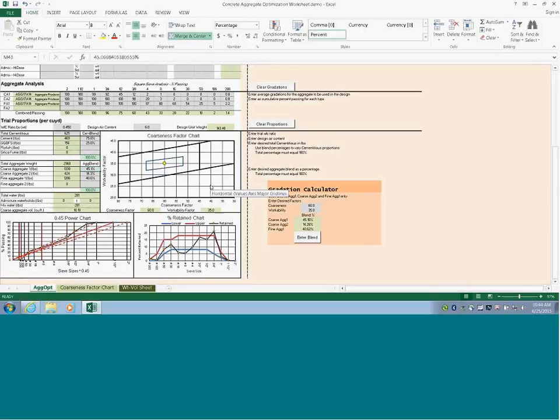What's the theory behind the modification of ASTM C157 with the 14-day wet cure? I'm not sure. Well, that's one of the things we need to really evaluate during this pilot program, which is why you have problems making the 500 micro strain. We'll all work together on it and see where we go with it, because that's the one thing, you know, we probably ought to be doing things in accordance with the ASTM. If we're not, we need to do some experimental work before we go there.